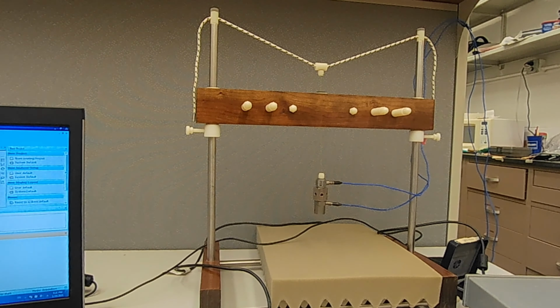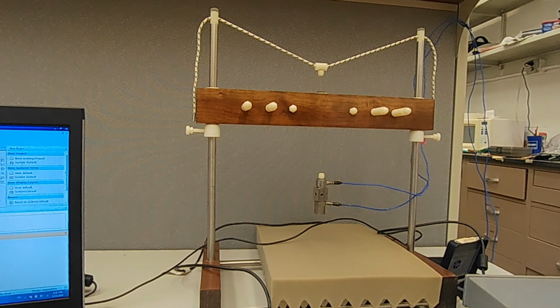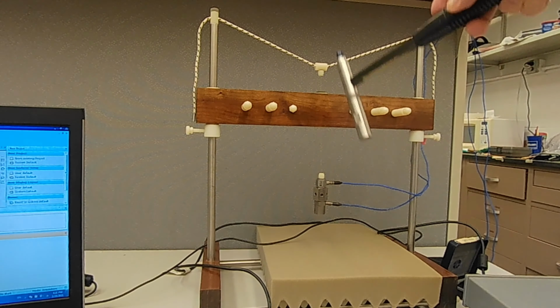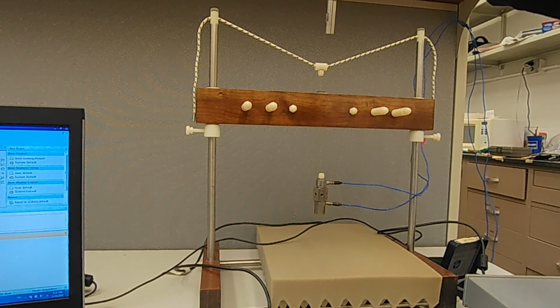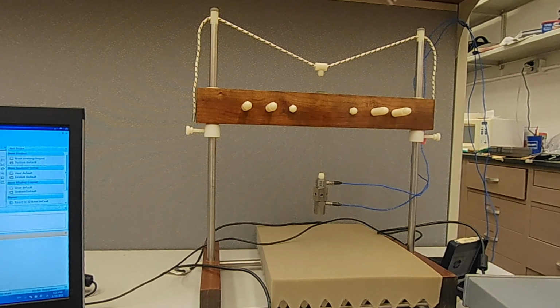And what I'll do is I'll have my hammer, which I'm going to hit at this junction point, and we're going to have the acceleration results recorded along with the load cell measurements. And I will do this a couple times because I want to average my responses.